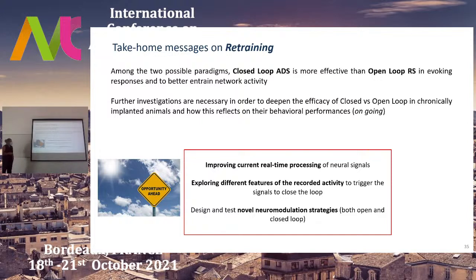It is also important from the technological point of view to improve the real-time processing of neural signals. We have been focusing on spikes, but also local field potentials, which are the low-frequency signals that you can also read, for instance, in humans, mostly with an EEG. The low-frequency signals can be used to improve the performance of this closed-loop approach.